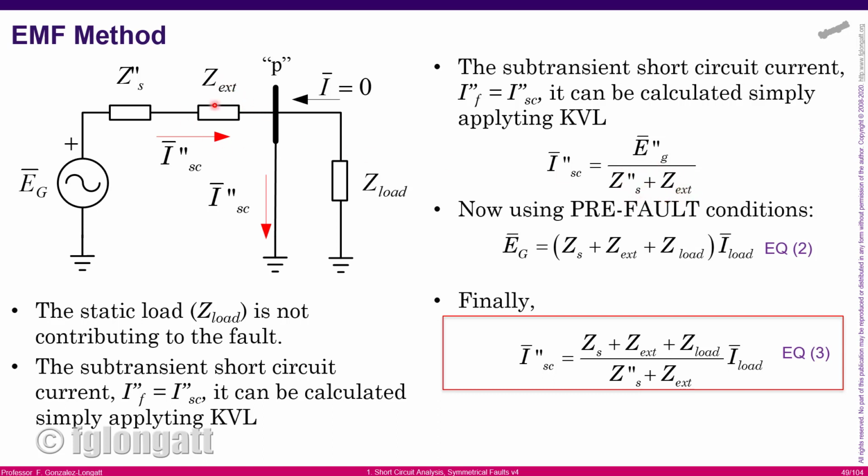A transmission line has a very small resistance because we don't want watts wasted there, and it has a very small reactance. It's the same for the synchronous machine. As a consequence, the voltage divided by this small impedance creates a very big short circuit current. Okay, good. Now what we will do is something very simple.